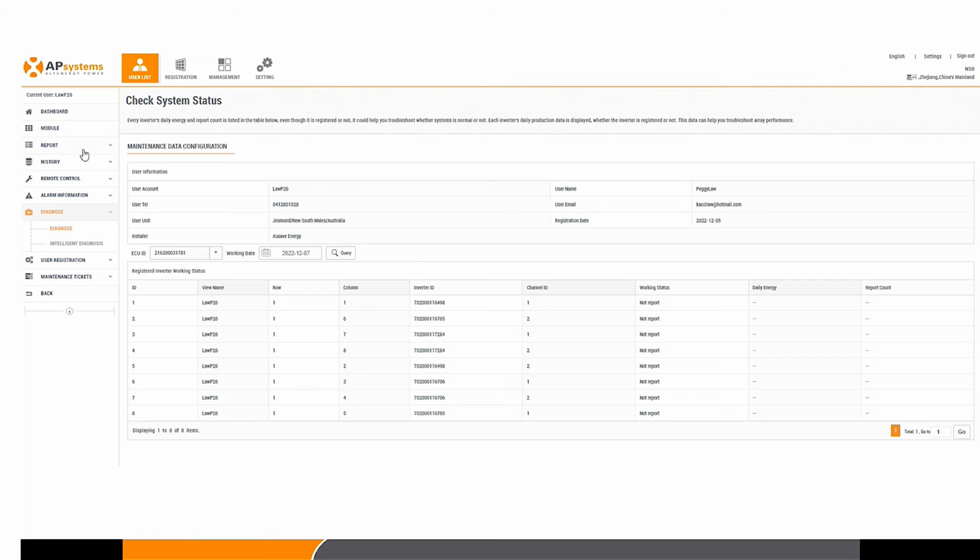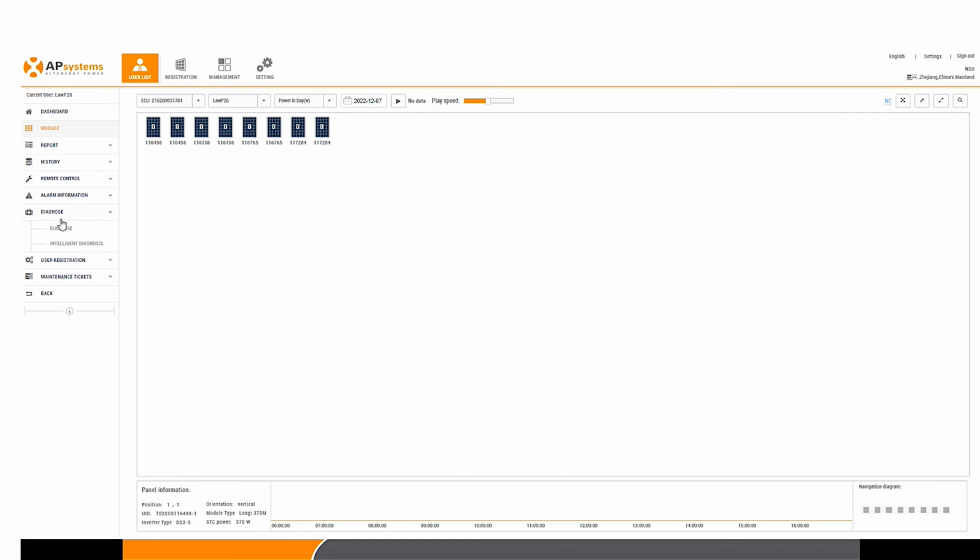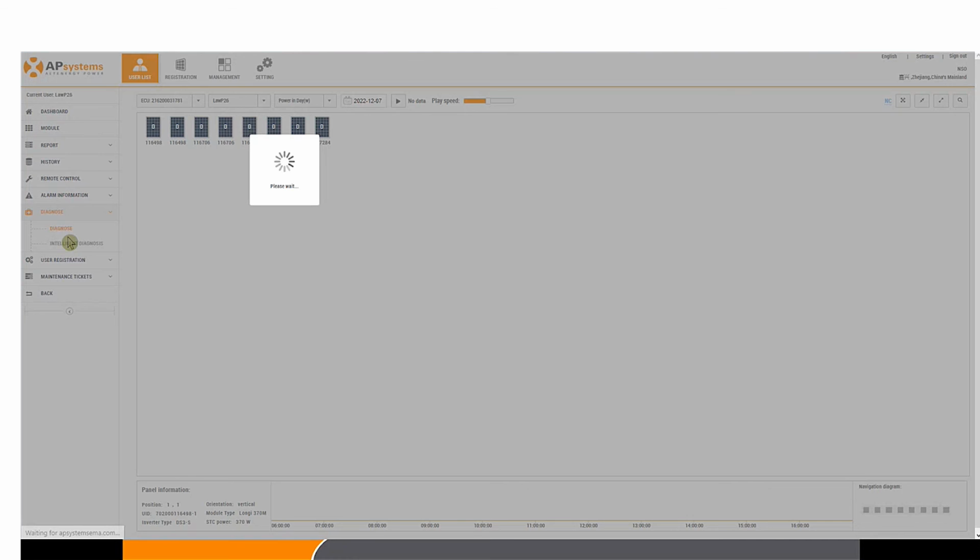So in this particular case, if customers like saying, hey, why is my system not working, not showing anything? It's because your unit's not connected to the server. Now, this is something that it's not really the customer's fault because, like I said, the ECU should be connected by the installer on site on the day anyway. So this shouldn't have happened in the first place if the installer have done the correct procedure by commissioning the system, plug it to Ethernet, or connecting it to Wi-Fi. Because if they've done everything correctly, this should not be blank.